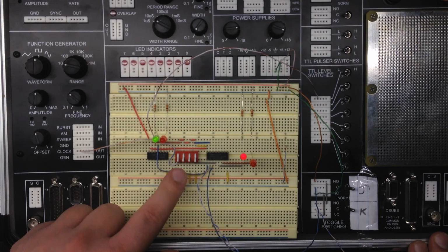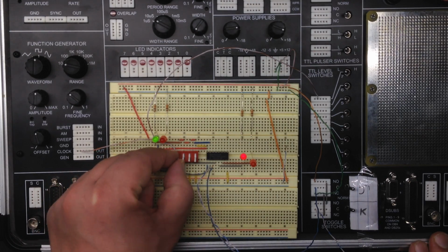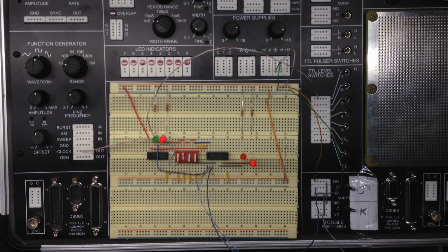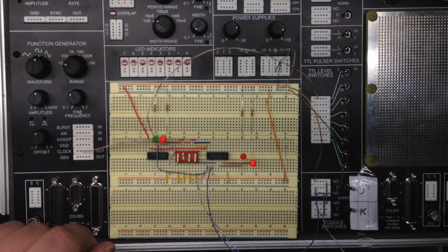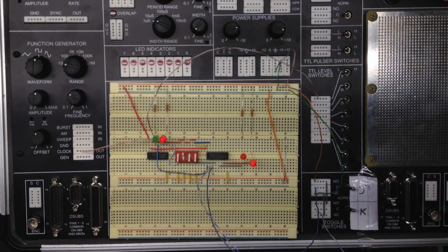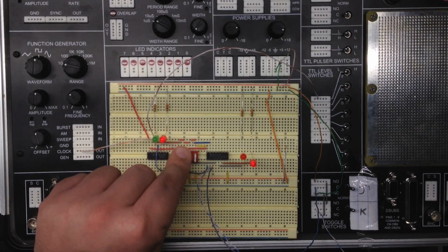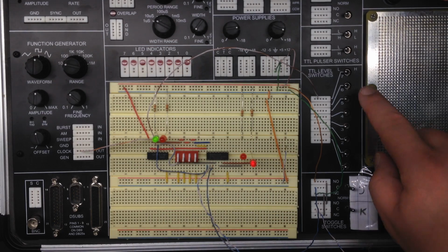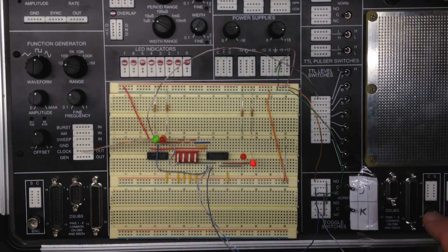Remember that the preset was switch number 2, so we should flip this up, which will represent a low, and we received the red LED turning on, showing a low signal on Q0 and a high signal on Q. This was exactly what we expected from the truth table. So we'll flip this back off, and we see that the state goes back to as it was, because the TTL switch for the D input is still on low.